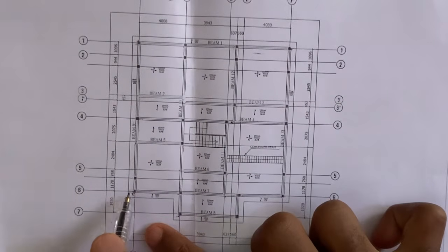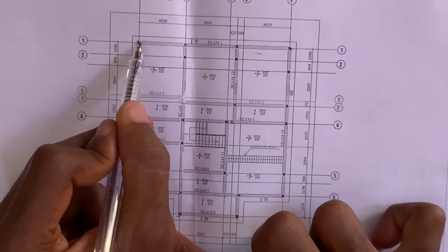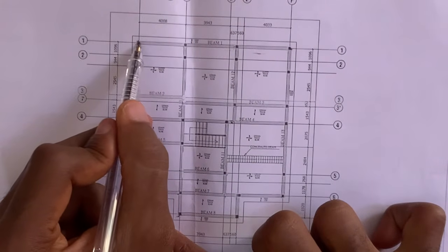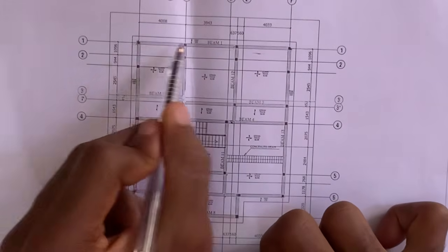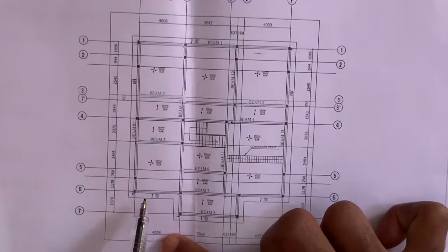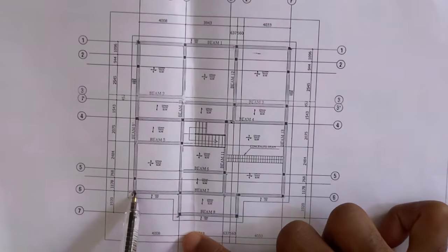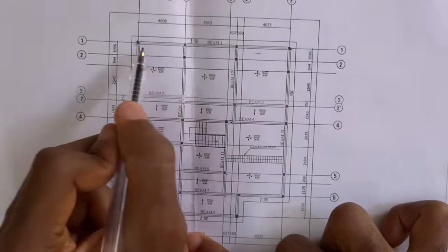Our dimension is center to center, meaning that this center to center dimension has entered into the perimeter that we've already calculated for our horizontal beam at beam 1 and at beam 7, right? Because half of the column has already been catered for at the horizontal beam at this point and at this point.